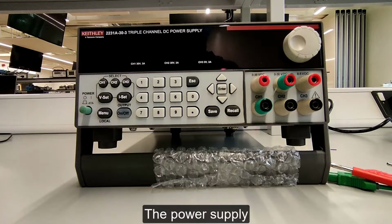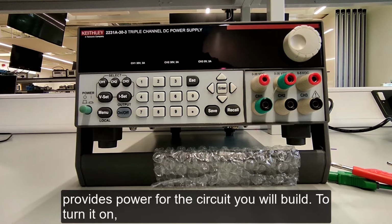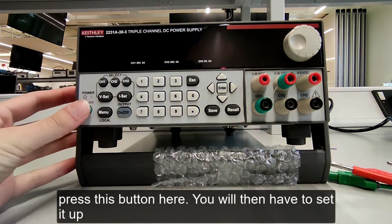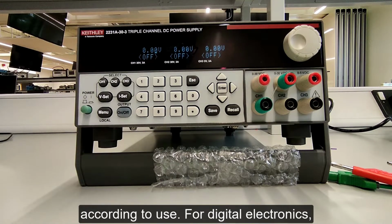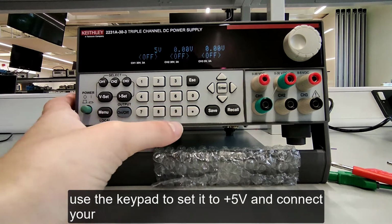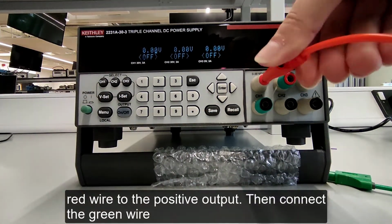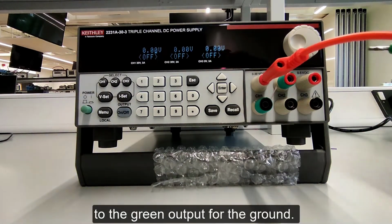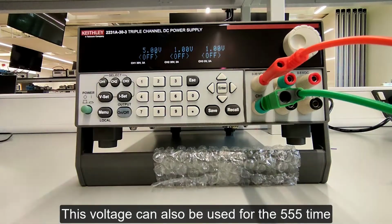The power supply provides power for the circuit you will build. To turn it on, press this button here. You will then have to set it up according to use. For digital electronics, use the keypad to set it to +5 volts and connect your red wire to the positive output. Then connect the green wire to the green output for the ground. This voltage can also be used for the 555 timer.